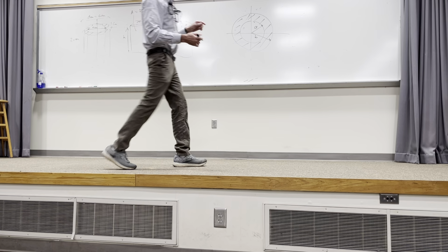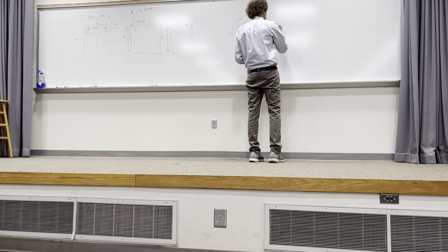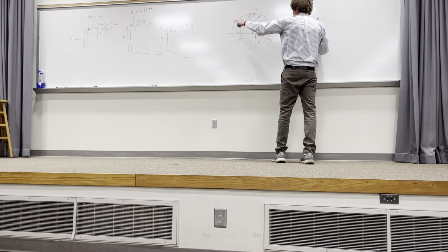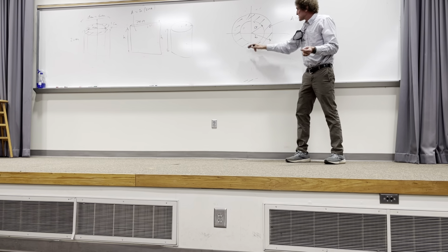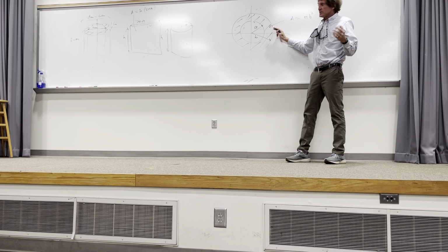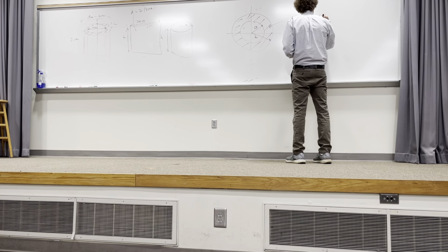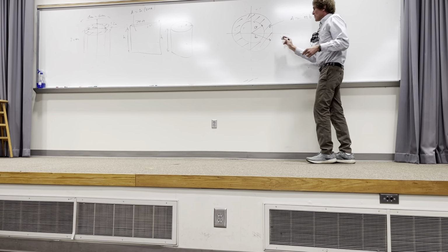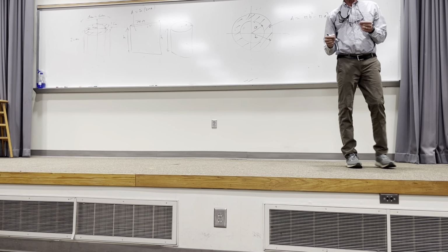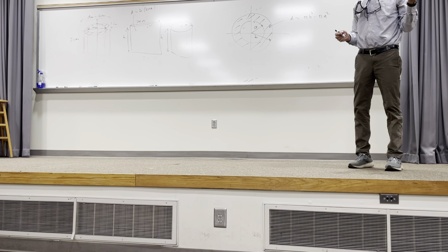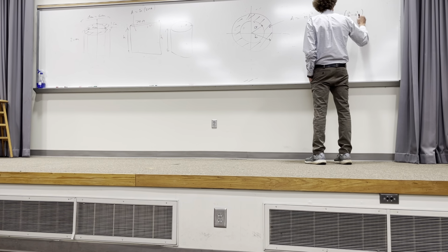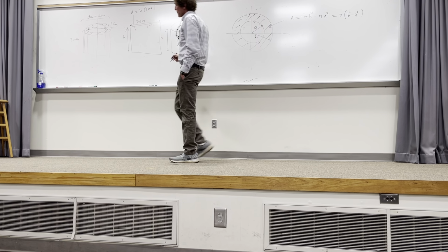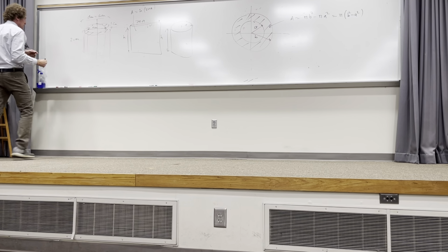So the shaded area would be the area of the outer circle, pi b squared, and if we subtract the area of the inner circle, the remainder is the cross-sectional area. So the basic formula is pi times outer radius squared minus inner radius squared.